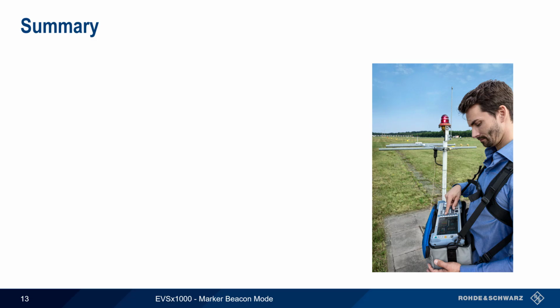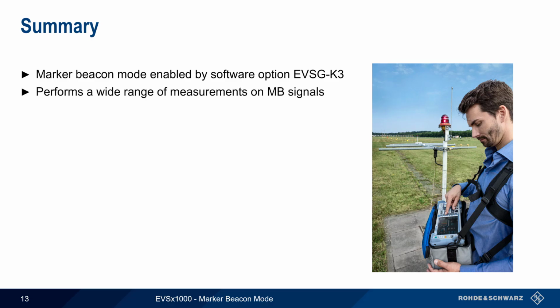In this presentation, we've covered marker beacon analysis mode, which is enabled by software option K3. This option performs a wide range of measurements on marker beacon signals, including the beacon frequency, modulation depth, and the timing of the dots and/or dashes used for each type of marker.